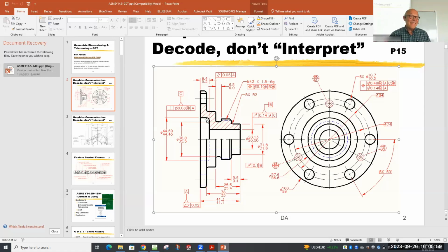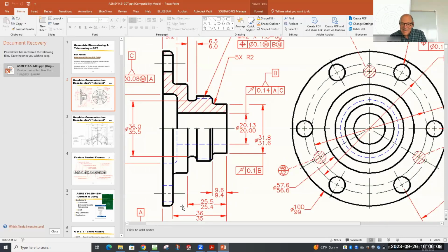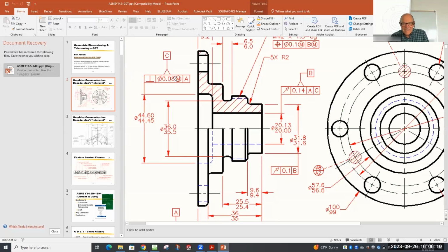That all makes sense? That's the fundamental concept right there of geometric dimensioning and tolerancing and max material condition, which is why if you take a look right here, it tells me this zone is fairly small, but it only applies if the hole itself is at maximum material condition. In other words, if I make the hole least material condition, I can make the whole thing crooked, more crooked, by how much more? By the difference between max and min, and max and least. In other words, if the hole gets bigger, now it's going to fit on there even if it's more crooked.